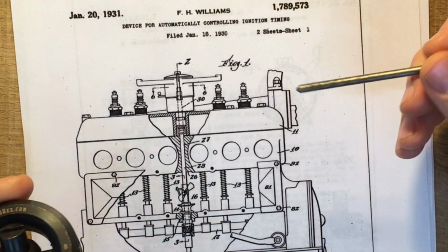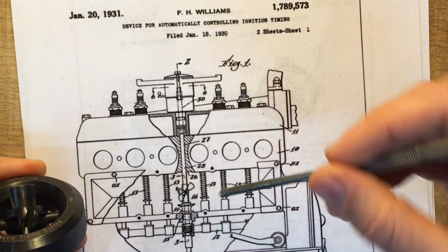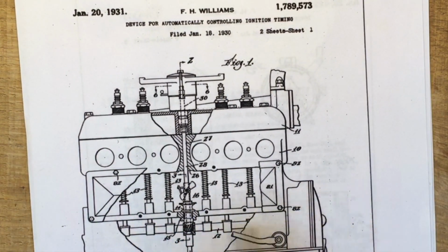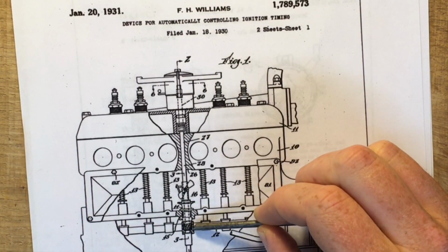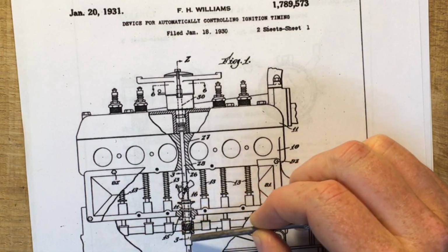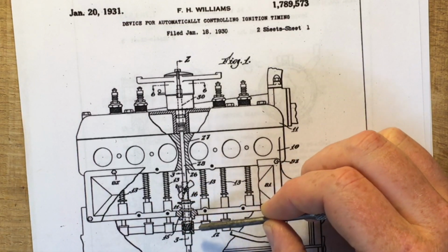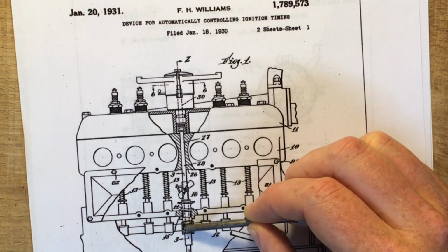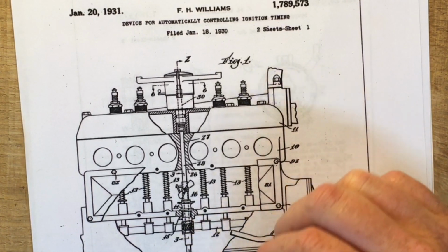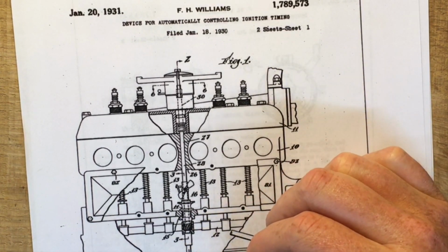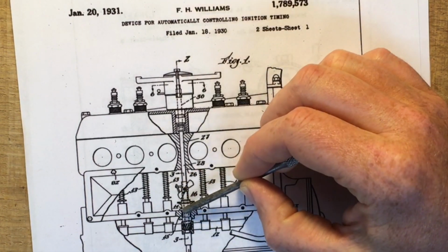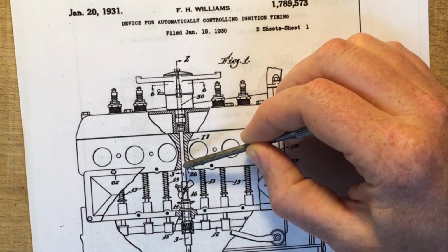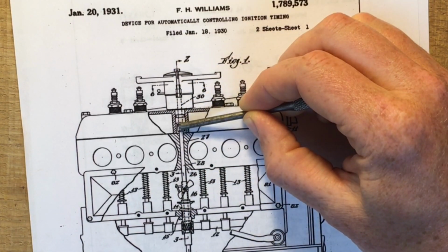Now, if you look at the drawing on the patent here, you can see kind of where this is situated in the engine. Here's your camshaft, running horizontally, and then on the camshaft is a worm gear, and then right here is the oil pump drive gear assembly, which has a helical gear at the bottom that meshes with the camshaft, and below this is the oil pump, and above this is a bearing, and then the lower distributor shaft, which connects to the upper shaft, which passes through the distributor.